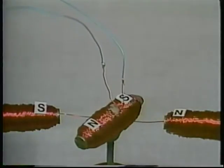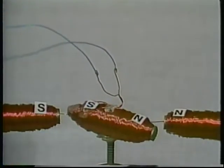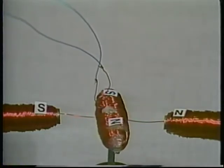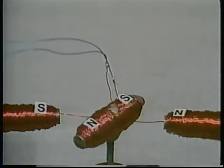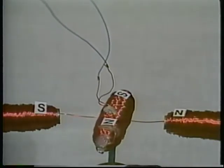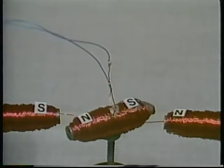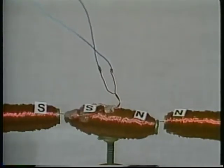Now we can keep the rotor turning by reversing the current in either the rotor or the stator coils at just the right time. The magnetic poles reverse and the rotor swings around to line up the other way, exerting torque as it turns. If we keep this process of reversing the magnetic poles going, north to south, south to north, and so on, the rotor will keep turning in a circle and exert continuous torque.